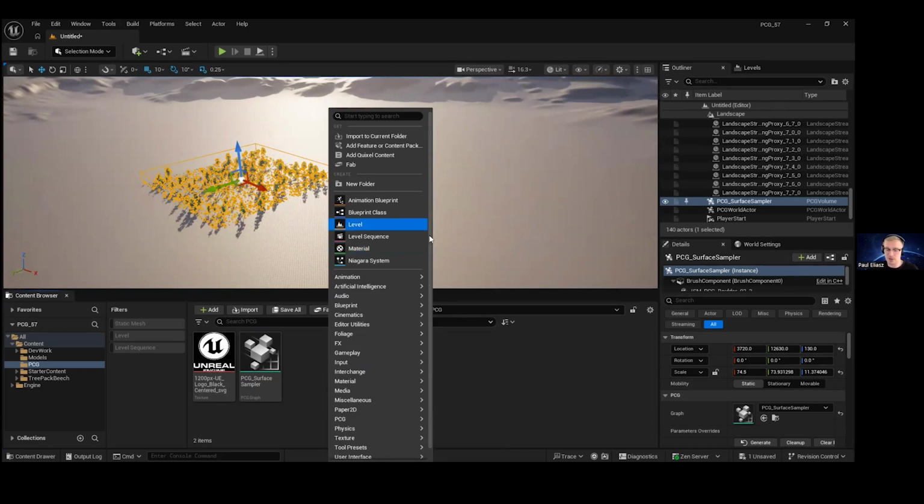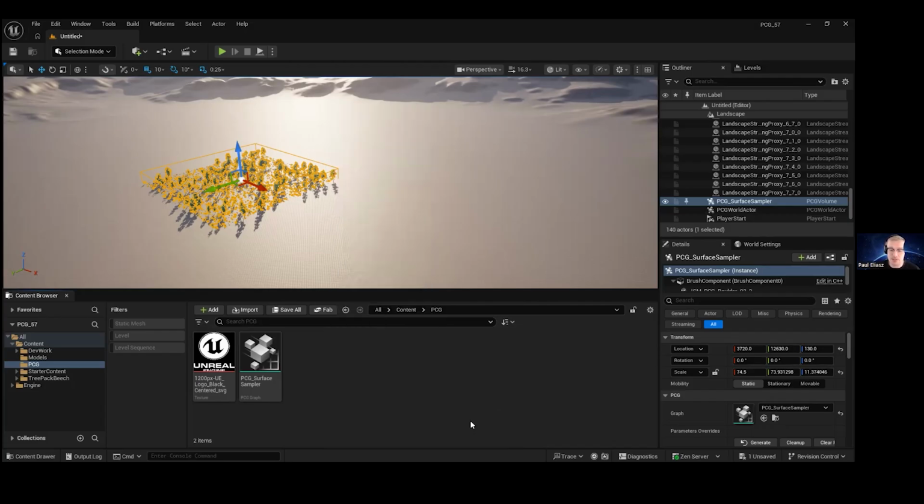Splines are also very cool because you can create roads or fences, or even, like we have here with the volume, within the interior space of a closed loop we can also generate trees as well as forests. But there's a caveat, because that also comes down to performance, and there are pros and cons of using splines for different use cases. Because I want to give you some options, I'm just going to show you how the PCG Spline works.